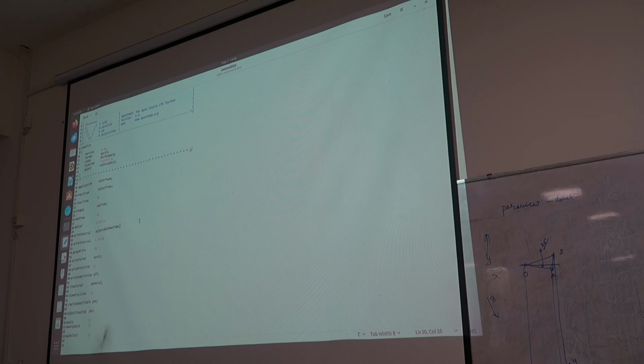Then adjustableRunTime, you know already the meaning, and then writeInterval, after what interval I need to write the data. So I am choosing 0.005 because if I choose a small time step, I will be able to observe the minor deformations that are taking place, and whenever I visualize it in the form of a movie, it will come out almost as a continuous thing. If I take large time steps, then in my movie there can be finite jumps.